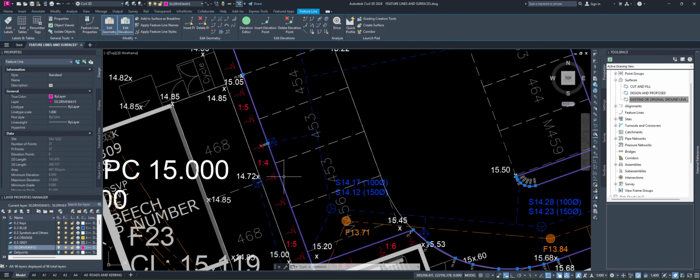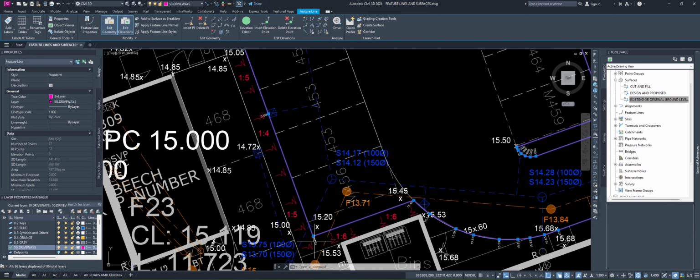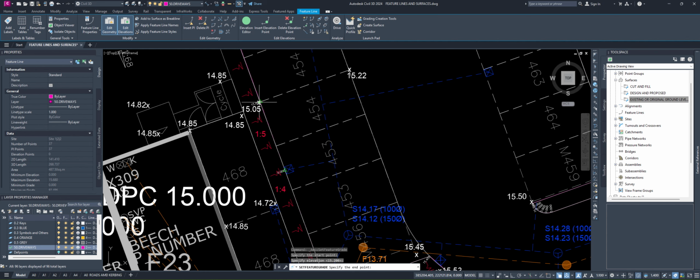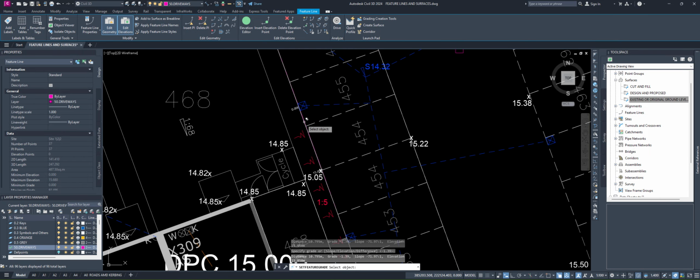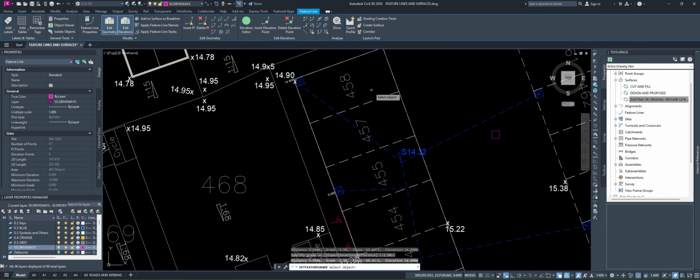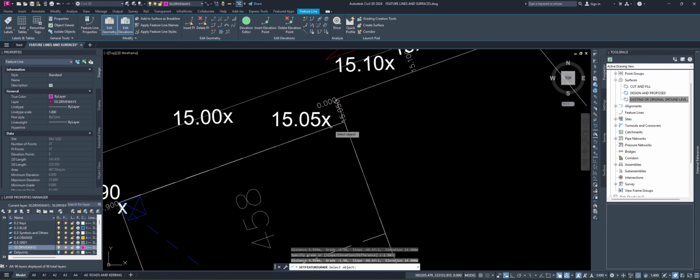Let's go back to our line work. What we're gonna do, we're gonna regrade between this point and that point. Okay, let's click that point, skip that, go to the next one where we got proposed level, click OK, and OK again. Okay, I'm not gonna go out from the command, I'm gonna carry on going until I got everything fixed.